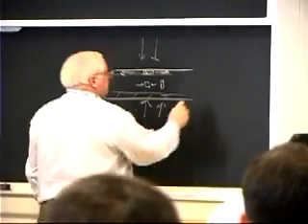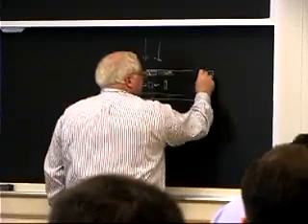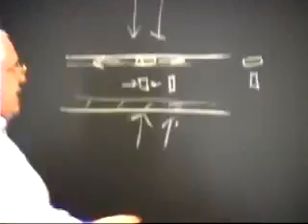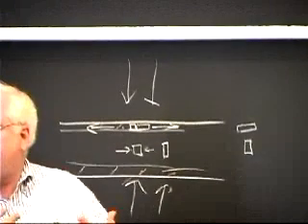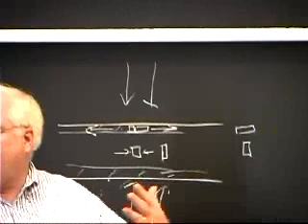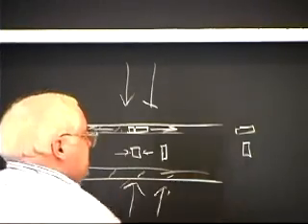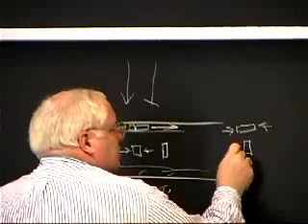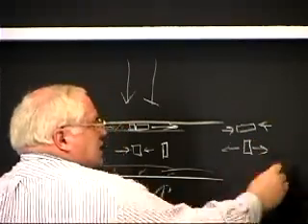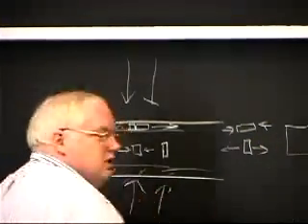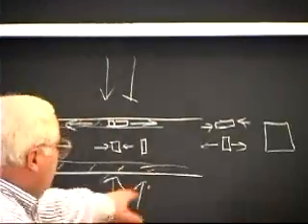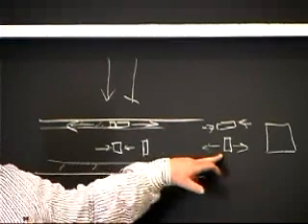Now I put something together like this and like this when it gets down to room temperature, but in fact they have to have the same length on this edge because they're all tied together, right? So what do I have to do to this at room temperature and this in order to get them to form a big square that's all one solid piece of material? I have to put this one in compression and this one in tension.